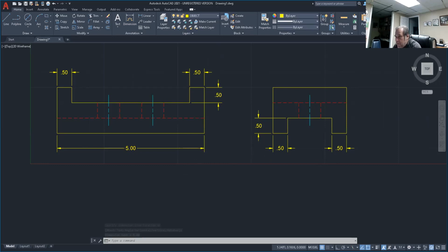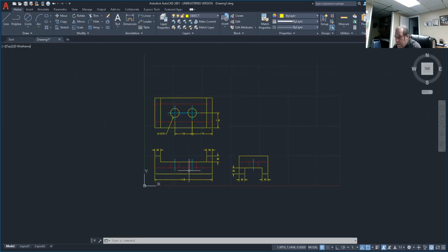Okay, now I've got to give the height. So I could put the height here, here, here, or out here. Now, to me, it doesn't make sense to put it here or here because I might interfere with some of these. So I would say out here or out here, either one. Okay, and at this point, I'd probably start adding up my dimensions. I got 1, 2, 3, 4 in the front. I've got 3 on the right side.